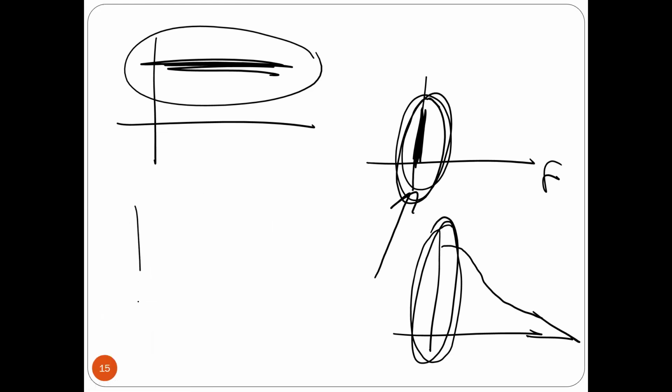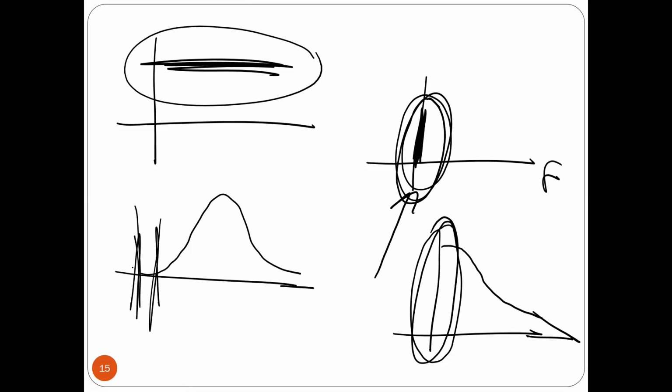For example, if this is a frequency domain, you have something like that. Is there a DC component here? The answer is no, because I look at the small frequencies here, and the amplitude of the signal at the small frequencies is almost 0 or very small. So there is no DC component in the signal. Is that okay? Yeah, that's what I'm going to say right now.